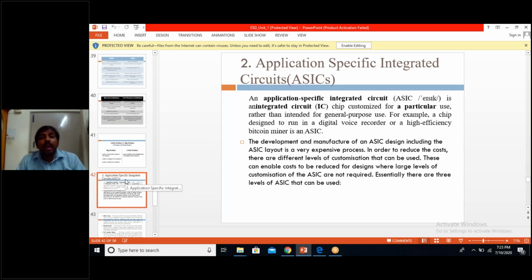So the main core of an embedded system is a processor. That processor can be general purpose or application specific. What application specific means is, depending on the vendor, he can design his own IC and customize it, doing the hardware design for generating a faster device with less power, high speed, and less area. Such requirements can be met by ASICs, application specific ICs, and that depends upon the purpose.